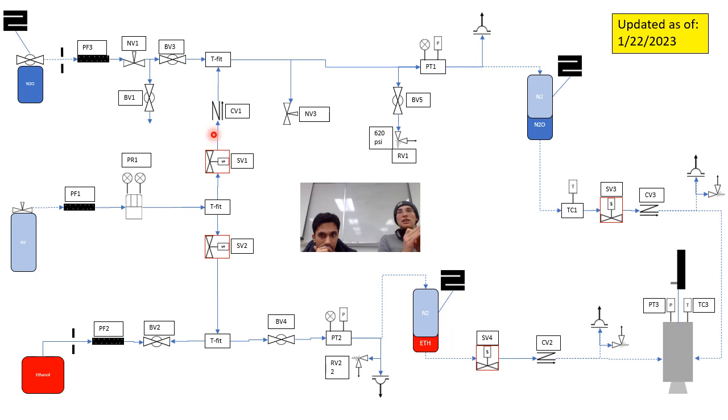But assuming that whatever process, it could even be an automated process, says yes, we have the flame catching fire and growing. We didn't just extinguish it by opening SV3 and letting oxidizer flow in. Assuming that doesn't cause any problems, then we open SV3. Again, the details of this part are not as worked out. So we might just have to open SV1 and SV3 simultaneously. Maybe have SV3 open a fraction of a second early.